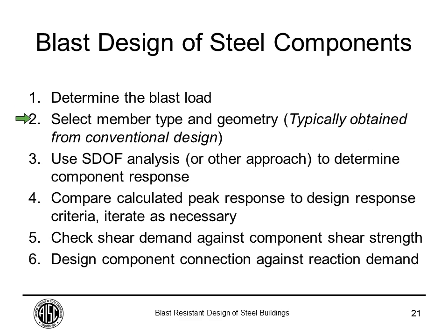Next, once you have your blast load, you want to have a member to start that you're going to analyze against that blast load. The design process for blast resistance design is interesting because we don't usually start from zero and start looking at blast resistance right away. I've always said to my architect clients and structural engineer clients that the best place for incorporating blast resistance into your design is, believe it or not, somewhere right at the 65% stage. Because at that point, most of the components have been designed for conventional loads and serviceability and some other requirements that are equally important.